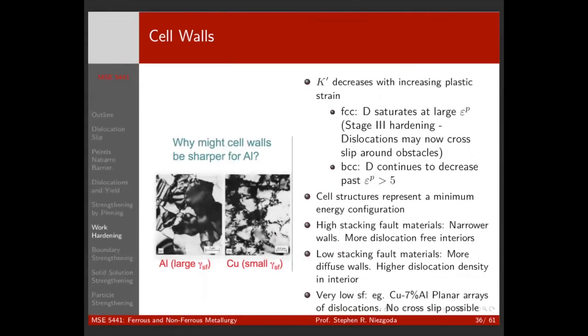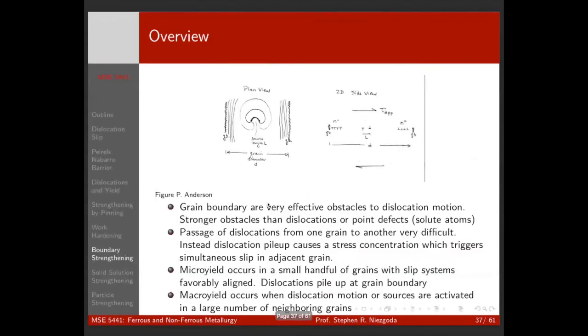So we talked about dislocations as being potent obstacles. Oh, I guess I should just say, obviously it makes sense that it's harder to get a dislocation through the cellular structure than it is through a field of individual dislocations. It's not easy to derive what the pinning spacing should be, right? But the square root law seems to magically hold still. That's another interesting question, why does the Taylor hardening law hold when we have a cellular structure rather than individual defects? Damned if I know.